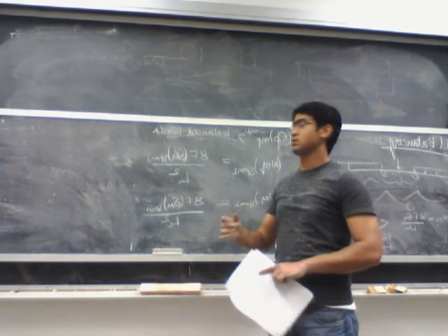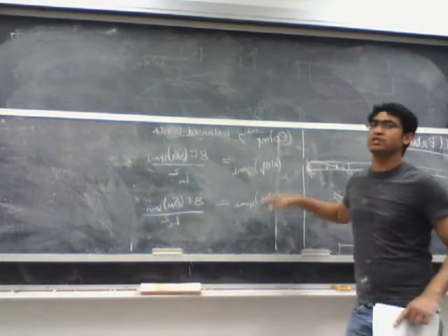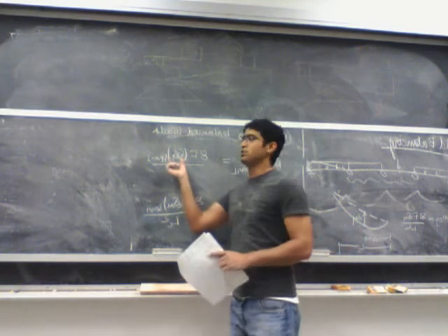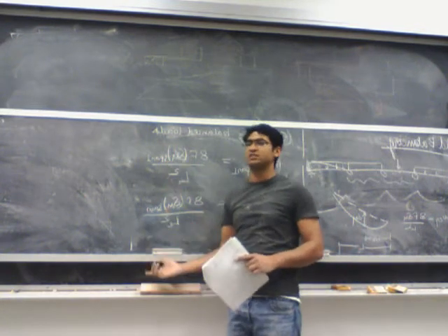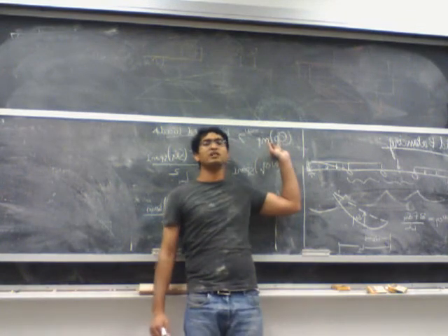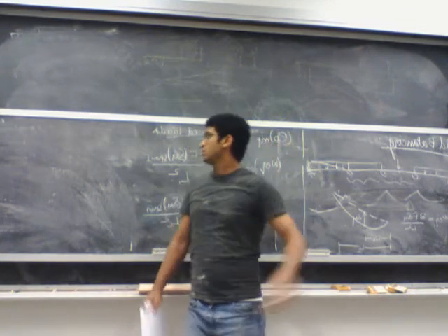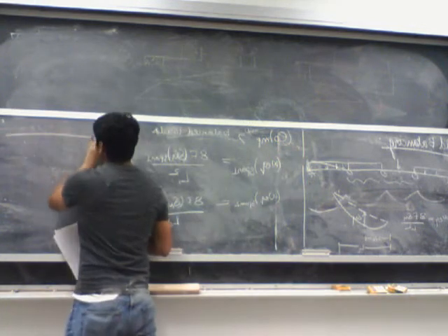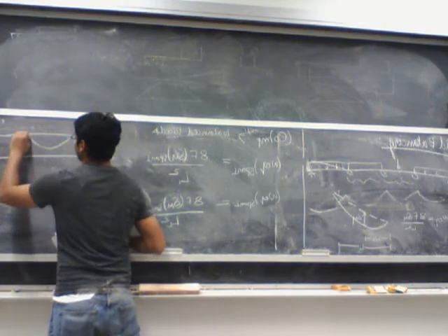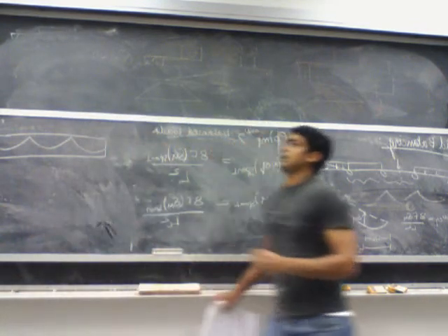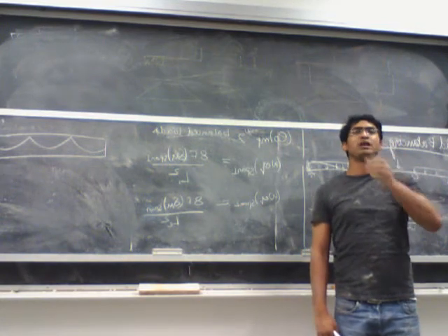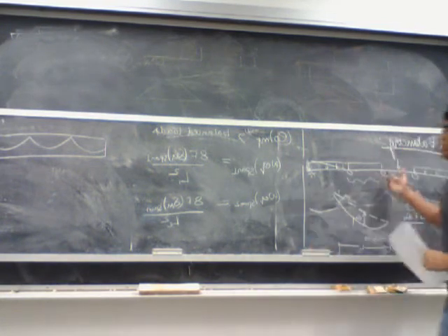Say it again. So once you have this equation for the equivalent load for each one of the spans, now what you need to do is relate this delta M for each span to its E naught, because what you have is a limit on the E naught, not delta M. So what you do is you assume a tendon profile, and in order to assume a tendon profile, you can assume that the tendon profile will be similar to the moment profile due to these equivalent loads.